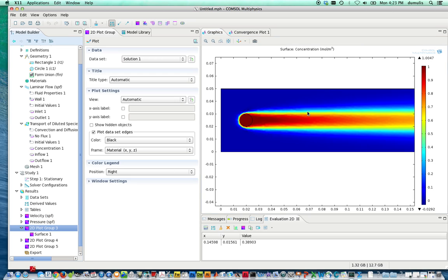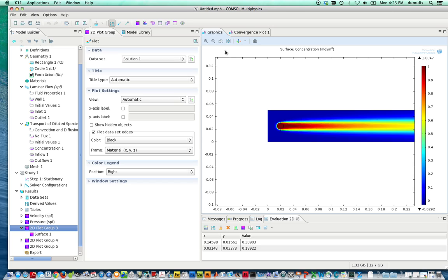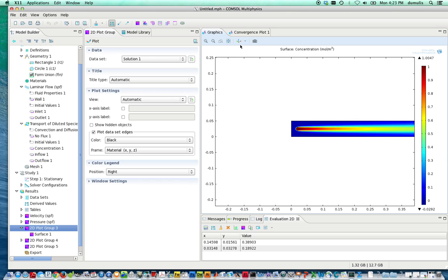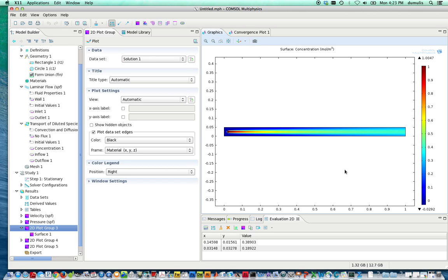So here's what the concentration distribution looks like now when we reduce the diffusion coefficient by an order of magnitude. It takes a lot longer down this distribution for diffusion to dominate. The number that captures this ratio is the Peclet number, and it's the ratio of the diffusion time to the advection time in this type of domain.